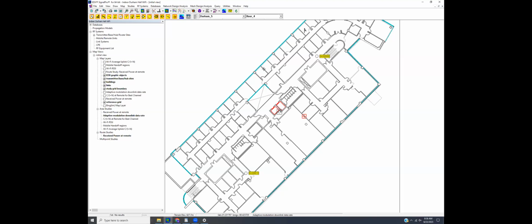And I did the same thing for the door sweeps, and I took the elevators through the middle of the building here, and I changed those to be a solid metallic obstacle, so to model the steel elevator case and kind of the additional signal blockage that you get from that. And then I put glass as the material type for the exterior glazing here.